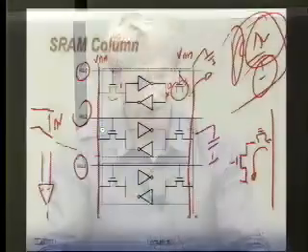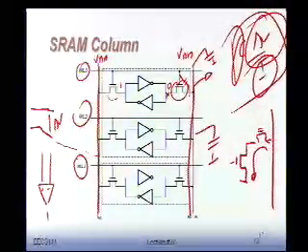that bit precharging, actually, start thinking about it. When you precharge your bit lines during a read, you look at the cell and say, hey, I look at those transistors. You start thinking about how should I size my transistors in my cell? How should I do that?